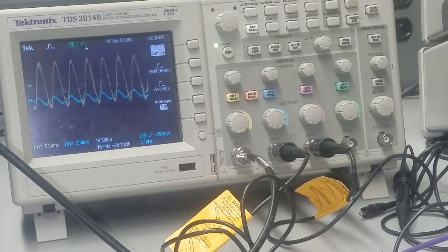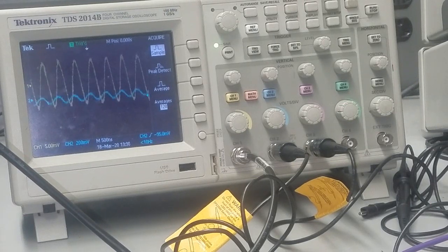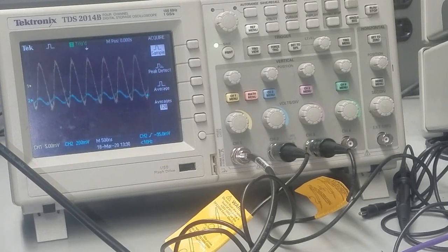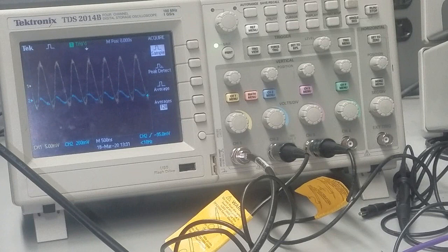The low cutoff frequency is caused by the coupling capacitors. The bigger the coupling capacitors, the smaller the cutoff frequency is going to be. And the high frequency cutoff is caused by the internal capacitance of the transistor and the parasitics, the stray capacitances of the breadboard, which are very, very small capacitances. This is a very good practical hands-on experience of how the circuit will work.